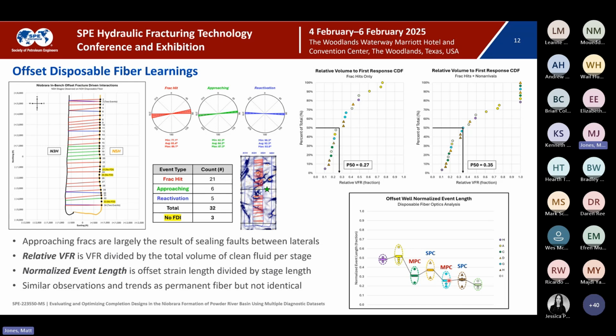Here, it is very subtle, but you can still see the very small uplift from going from multiple perforations per cluster to a single perforation per cluster. This is where it actually flips. So what appears as though it is good near wellbore treatment uniformity for design I may not necessarily translate to good far field treatment uniformity. So that's the only thing that's not necessarily aligned between the diagnostic tools.